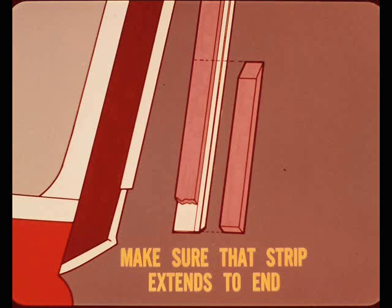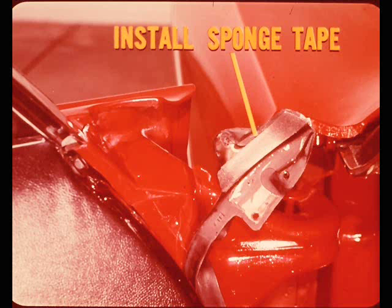For minor corrections in pillar weather strip contact, you can shim it out by cementing a strip of closed cell sponge seal tape between the weather strip and its retainer. If extra shimming is needed, insert the sponge tape between the pillar and the weather strip retainer. You can open an air leak gap if you don't make sure that the retainer shim strip extends to the end of the retainer. Even without a shim, the existing foam seal strip must also be flush with the retainer end to seal properly. Good points, Tech.